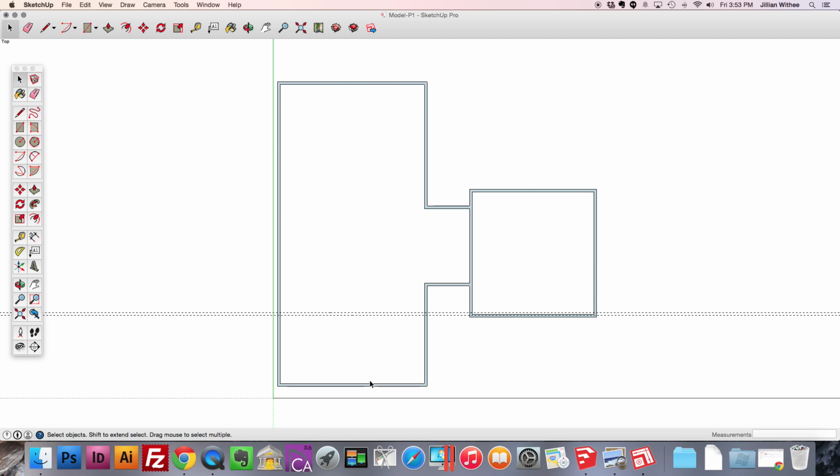And since we're drawing an orthographic drawing, the plan of a fairly regular house, we probably want most of our walls to be at 90-degree angles to each other, unless they're specifically angled or curved. So the reason I have you start out in parallel projection mode when you're drawing is to make sure that those lines are straight.